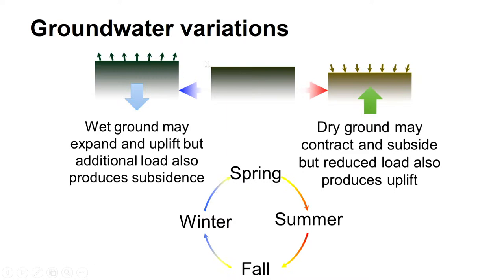Then you can see the groundwater variation. Groundwater variation is basically due to loading and unloading, there is an elastic variation. So compression is there and relaxation is there. This compression and relaxation causes changes that basically change your monument setup, base station, our campaign station. That's why. And it mainly happens when we are looking at yearly data. So when you see the yearly data, you will clearly see this groundwater variation effect in your data.